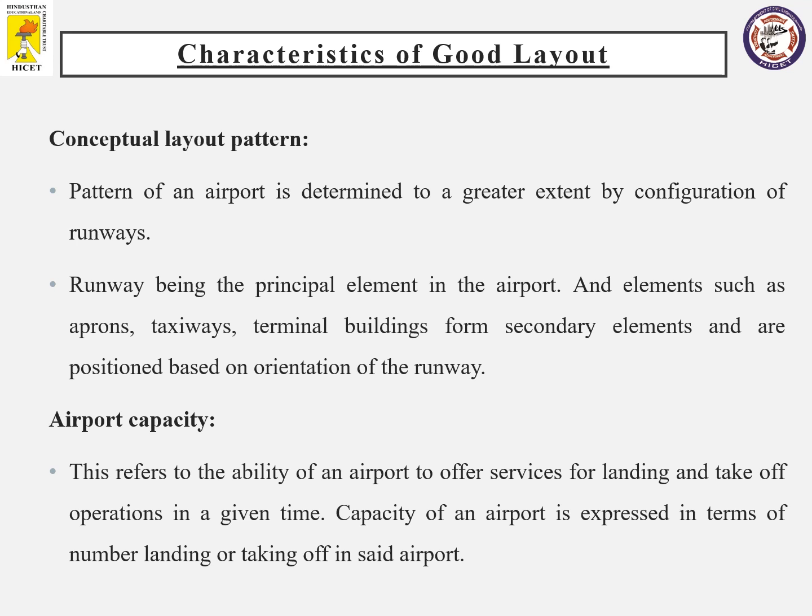For a good layout, conceptual layout pattern is very important. You have many designs, alternate designs, and comparing all the designs, you are going to finalize one design which is the most optimum one. And for the most optimum one, it is totally determined by the configuration of your runways. Configuration of runways is nothing but deciding the number of runways and placement of runways with respect to your windrose diagram, or according to the wind condition there. If you are able to place your runways very clearly in the airport, other elements like aprons, taxiway, terminal buildings, which also form the secondary elements, can be positioned very correctly in a good layout. So to form all these important things, the runway configuration is very important.